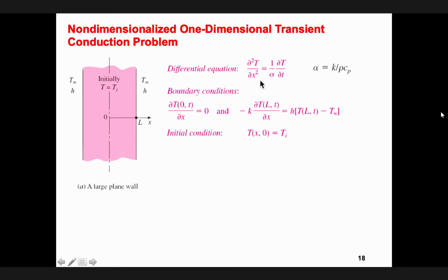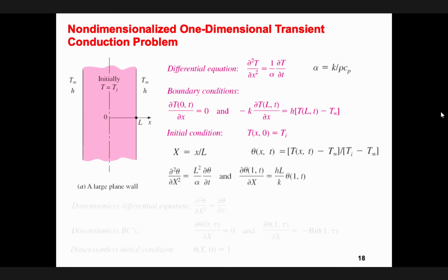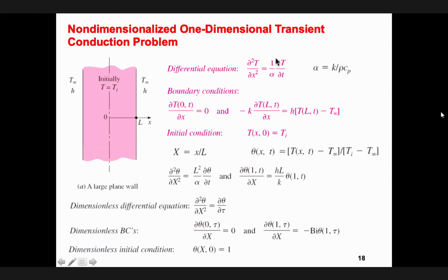Now, we have to solve this partial differential equation, because it's a function of time and x, considering these 2 boundary conditions. I'm not going to do it, but I'm going to go through it quickly. This is math. You had it in EMAT 233, and the best way to do it is to normalize it or use dimensionless variables, because the solution can then be applied to any x and thickness and so on. Therefore, we normalize it, and by change of the variable, this equation now becomes dimensionless. Therefore, it doesn't depend on what the temperature is, 20 degrees, 40 degrees.